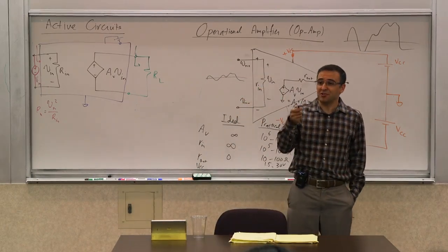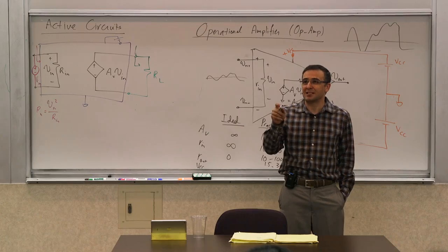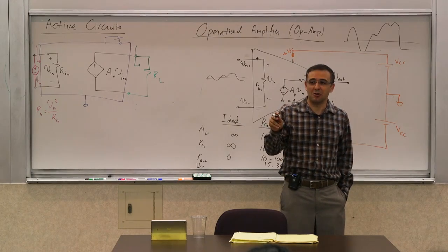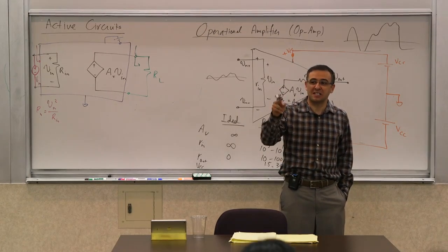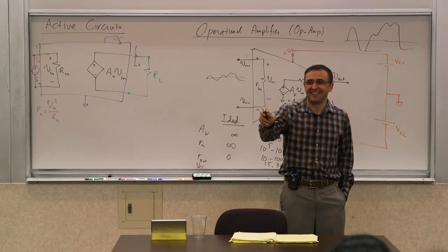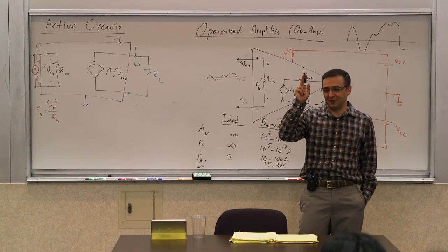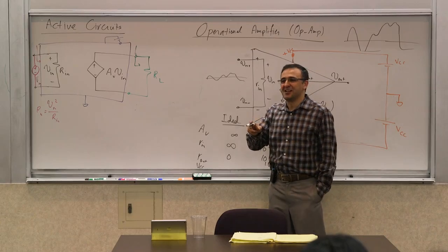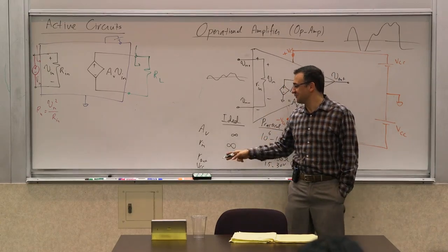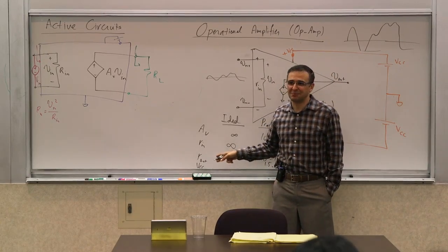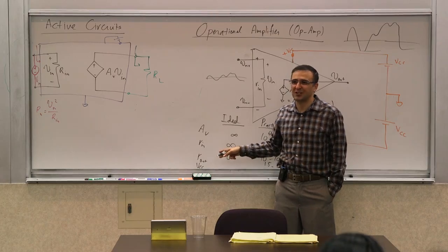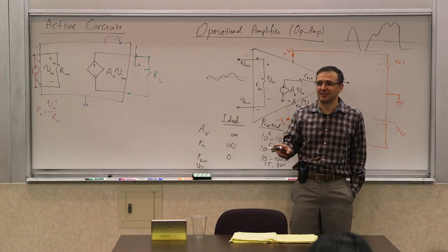Well, from the energy consumption perspective, yes. But remember, if the VCC is 0, then the current is infinity. What you said would be useful if you didn't have conservation of energy. If you make the supply voltage 0, then to generate power, it needs to draw infinite current, which is not a good thing.